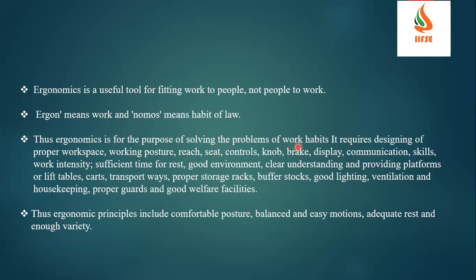It requires designing a proper workplace. For example, I have a machine. I have one control here and one control at 10 feet distance, and I have a raw material storage area at 15 feet distance, and I have a tool stand area. I need to change my tools every half an hour, each operation, or each 10 pieces. I have a tool stand at 20 feet distance. What will happen? The operator always has to move 20 feet, so he will get strain and will not perform effectively.